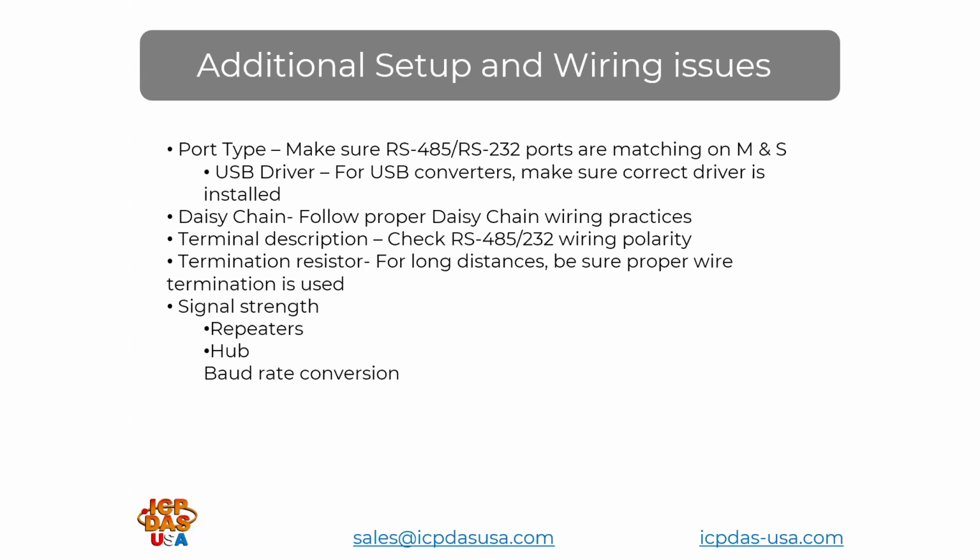We call our RS-485 terminals data plus and data minus. Others call them A and B, where B is actually the plus terminal and A is the negative. So it's opposite to what I would think, but that's just how they have labeled it. I've also seen them called RS-485 plus, RS-485 minus, but the main thing is you need to pay attention to the positive and negative polarity. Sometimes you need to connect a jumper as well.